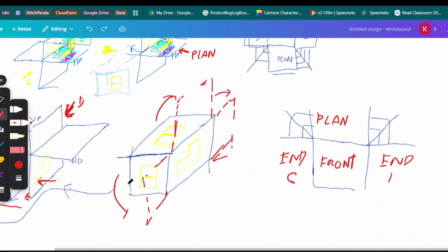You know they're looking at it from the C direction if it's on this side. If it's on this side, and you know it's third angle projection, because you see the third angle projection symbol, then you know that it's from D.